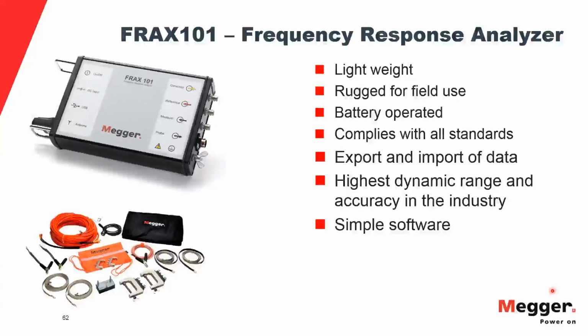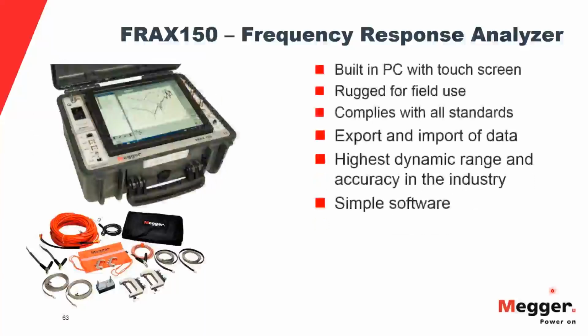And then a couple accessories, as I mentioned, you want a known reference. So the field test box comes standard with all the Frax units, just to verify the instruments work in all frequency range. And then we also have an optional accessory that's the field demo box that you can use as a training tool, and you can simulate a variety of things. You can mess with the core, you can clamp a winding down, you can short a winding, you can lose turns, different things like that.